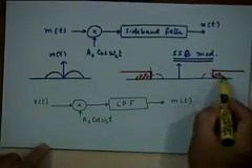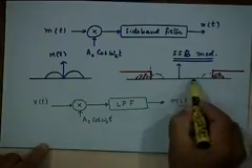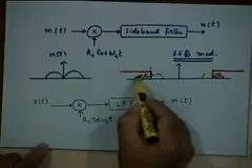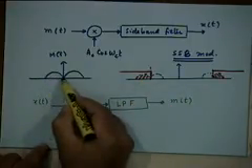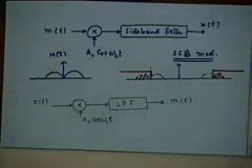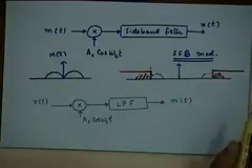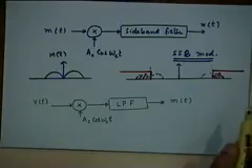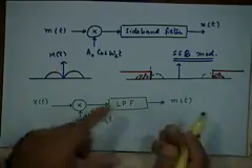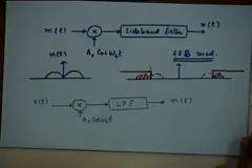So let us say you have this component. When you translate it by minus fc, what happens? It comes here, and this portion comes here. So you get this baseband spectrum that you wanted, and the plus fc component goes to the neighborhood of 2fc, right, which will be eliminated by the low pass filter. So there is absolutely no difference in the demodulation process.